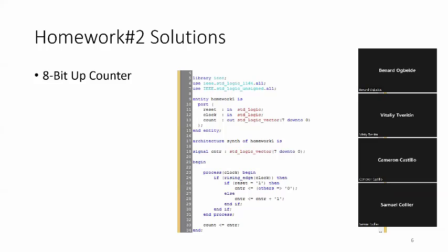Then what? Okay, so after you say begin. By the way, reset is the same as clear. Okay, very good. So you can say clock, comma, clear, then begin, and then say if. Yes. Clock, comma, clear. So it should be one of the triggers for the process. Exactly. So as long as it's triggered first, saying, for example, if clear is 1, then D out goes to 0. Excellent. Thank you. No worries. Thank you.